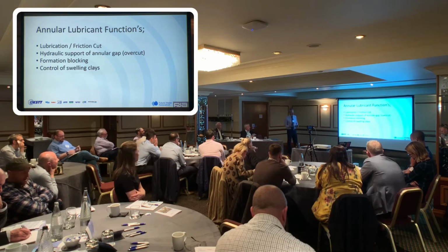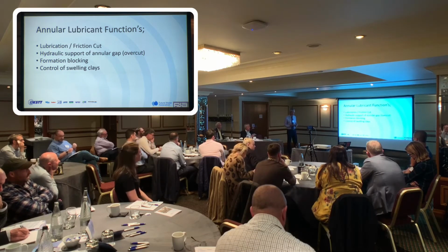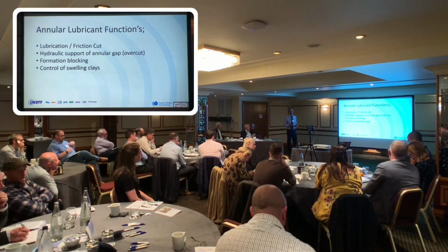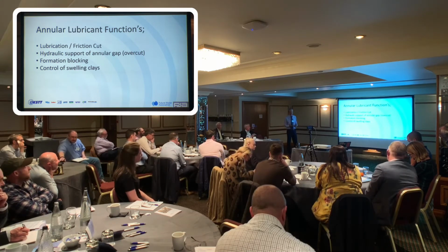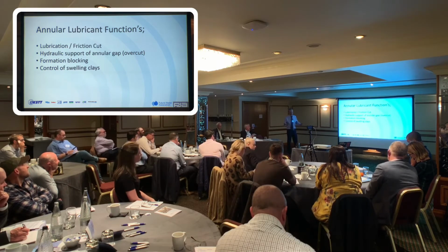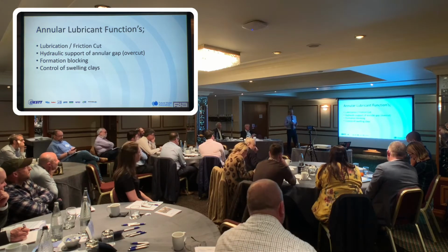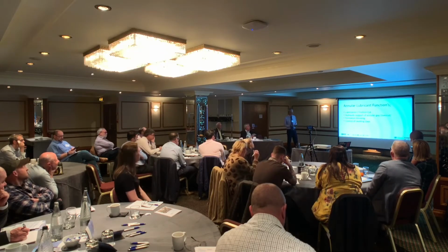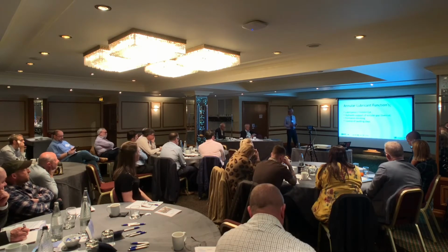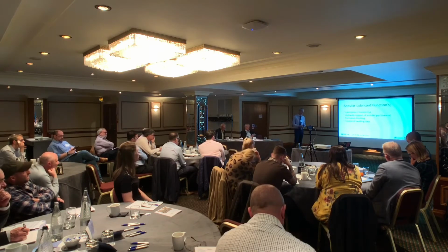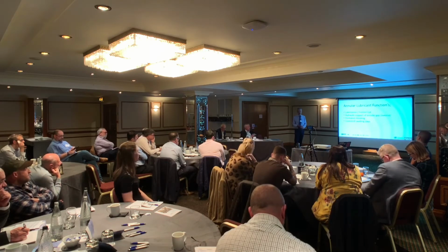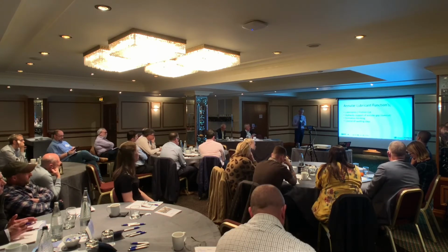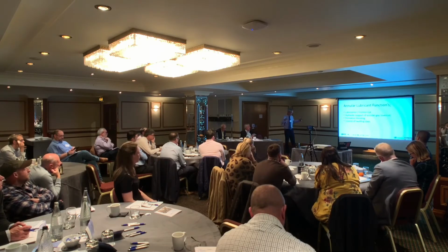In some grounds, like in open material, there's very little you can do to actually fill the annulus. In a gravel, if we're honest, the gravel drops straight onto the machine as you cut it. You can't really support it. You can inject behind the overcut, and you will get some void filling, but in general, the lubricant there is purely for lubrication. It's not supporting the annulus, not in a gravel. It will do if there's clay content that's locking the gravel together, but in an open ballast, it's like a bucket of marbles. They'll just fall onto the pipe.